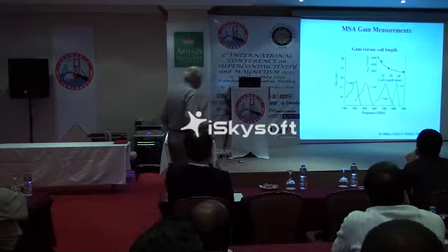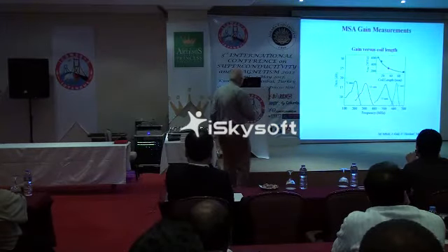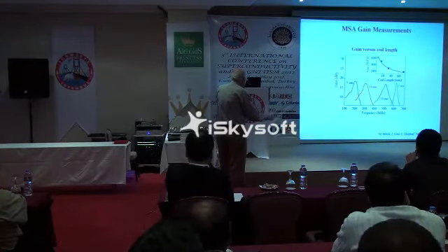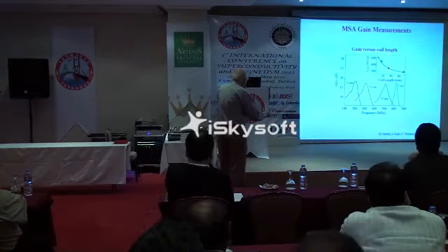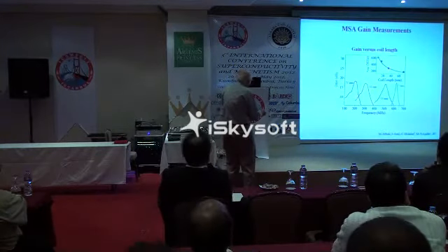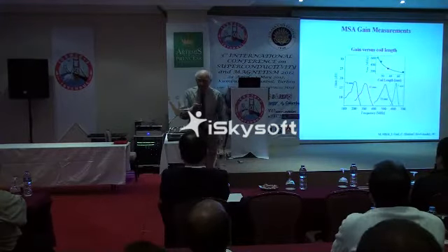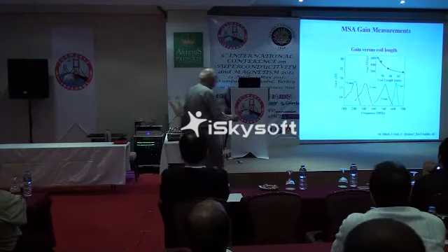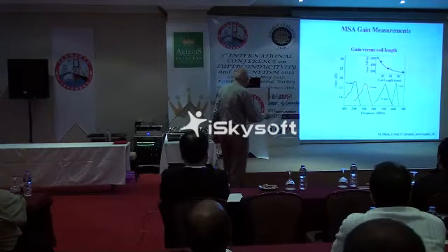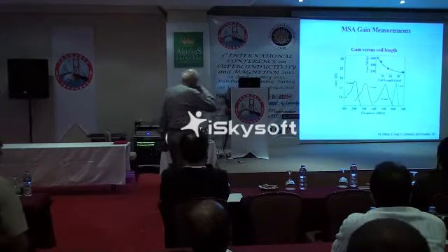And indeed, that's what you see. This, in fact, was the first set of data that we published. Here we're plotting the gain of the amplifier versus frequency for 4 different coil lengths. And what you see is that as we progressively decrease the length of the coil, as you would expect, the resonant frequency moves up. And in this particular case, we've got something like 18 dB of gain at 650 megahertz.